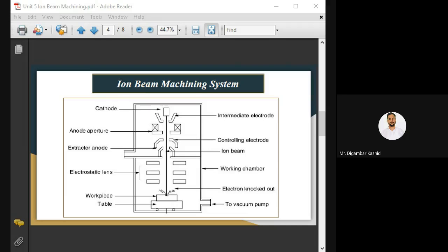When an ion strikes a cluster of atoms on your workpiece, it dissociates between 0.1 to 10 atoms from the workpiece material. Due to that, this process permits accurate machining of virtually any material.